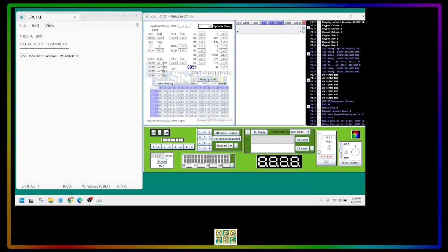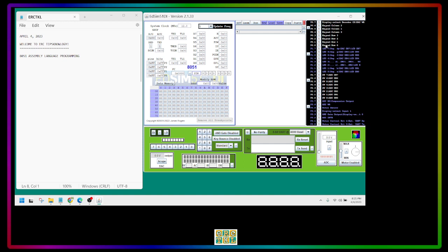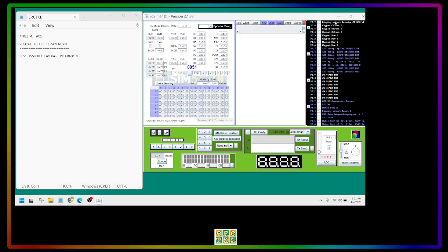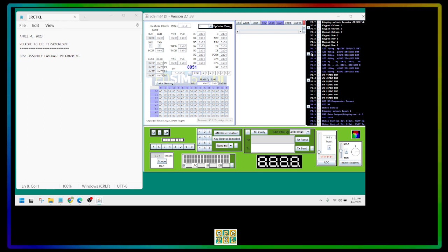And for this particular simulator, the port zero pins, P0.0 up to P0.7, are fixedly connected to keypad row 0 up to keypad row 3, and then we have keypad column 0 up to keypad column 2 and the display select decoder. Now, when we want to use the LEDs, we should use port 1 or P1 over here.